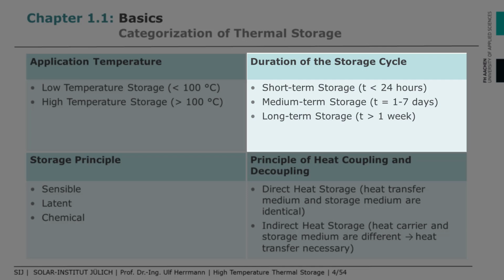Thermal storage systems are rather in the short and medium-term range. Long-term storage, such as seasonal heat storage, is difficult to implement at this temperature level. Besides some technical challenges, this is mainly due to economics. If a storage is charged and discharged completely only once a year, like with a seasonal storage, it must be extremely cheap. So far, this is only the case for a few low-temperature storage technologies, such as hot water.